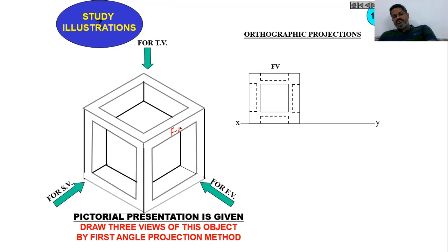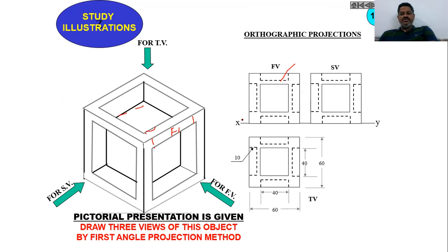But finally, we need to represent this dotted line in the front view, of course, as he has shown. In the middle, we have a material, so that is also represented as a dotted line. This dotted line needs to be represented, and at the bottom also we have one dotted line here. At the sides also we have dotted lines. So the side view, front view, and top view will also look similar to the previous component.